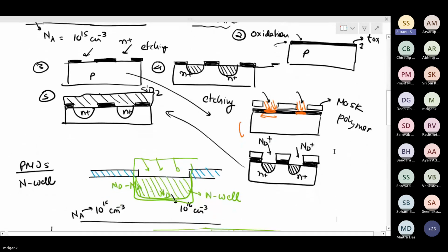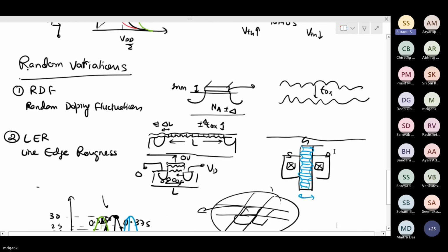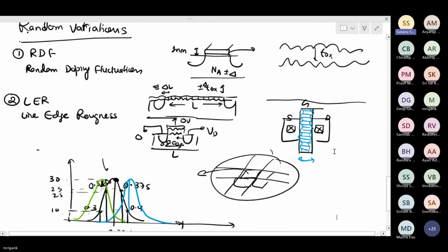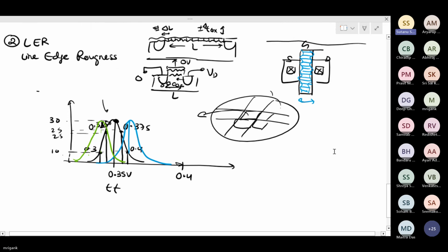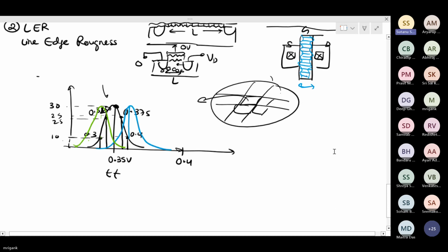Sir, I have a question regarding the last class. In the last class, you taught how to build amplifiers using a CMOS inverter, right? There we used a feedback mechanism, that is a high value resistor, to self bias the inverter. But my question is, if I bias the inverter using a current source, if I build a current mirror and then bias it using the current source without applying the resistor, then will it still act as an amplifier or will it have a lower gain? So that part you can tell me.